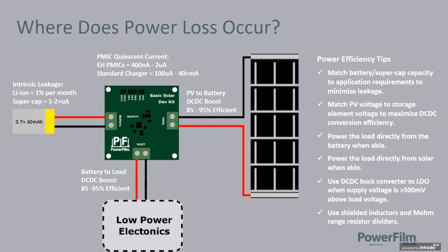And then a lot of applications, like Rich was saying, it all depends on the application. Sometimes you can cut out these middlemen, and you can maybe cut out the battery. You might cut out the output buck, the output converter. You could cut out the PMIC altogether. And every component you cut out, you're cutting out that little bit of power loss.